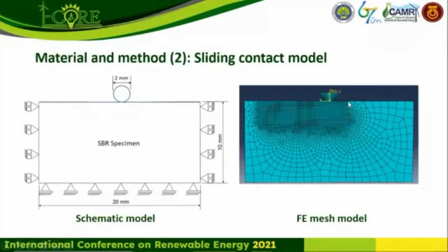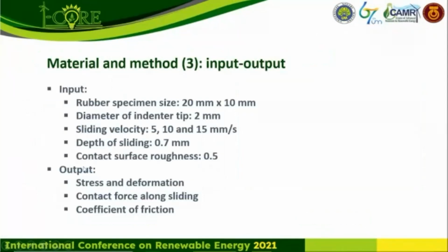Around the contact area, the mesh is very fine. We do this in order to obtain accurate results, like deformation, stress, and contact force, which are the input and output of the finite element simulation.